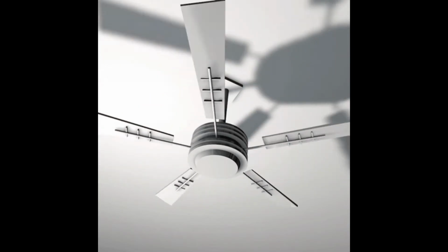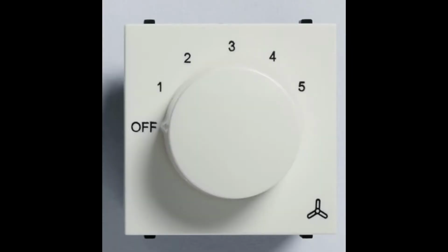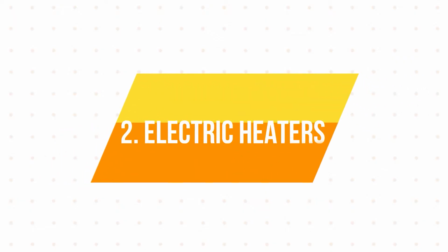The current flowing through the fan is controlled by regulating the resistance through the regulator, and then a circular knob on the component can be rotated to achieve a variable resistance on the output terminals. For any specific value of the input, we can calculate the resistance, current, and power flowing through using Ohm's law.